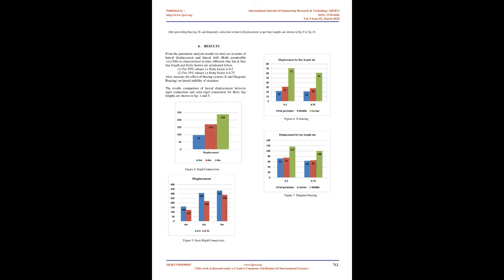By performing the parametric study of seismic analysis, they correlate the cyclic behavior of hybrid frame structure in terms of story drift and life safety. Anuraji and Hemlataji, 2018: their effort was made to find out the actual behavior of rigid and semi-rigid connection by performing nonlinear static analysis on a G+5 story structure in SAP 2000. From the analysis, story drift value and performance points were obtained.